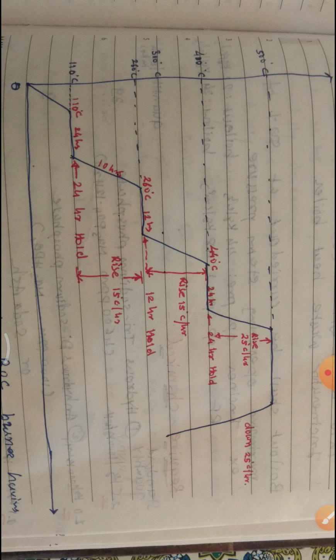Here in boil out, after starting boil out, send a CBD sample every 4 hours for checking pH, conductivity, TDS, phosphate, Fe2O3, oil and grease, silica and sodium. During boil out, also every 2 hours, IBD is given for 10 minutes. While doing so, take care of the level and maintain the level of the waste heat boiler using boiler feed water.